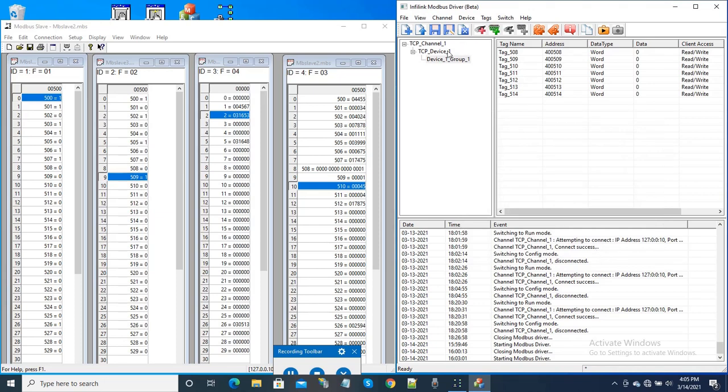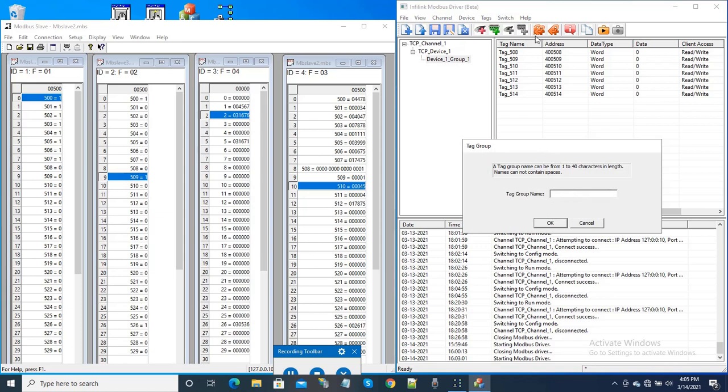So we now see we have a channel. In the channel we have a device. We have few tags in this device. We have a tag group included in the device. We can also have tag group in a group. To do that, I can just create this group create button and I can name that group.